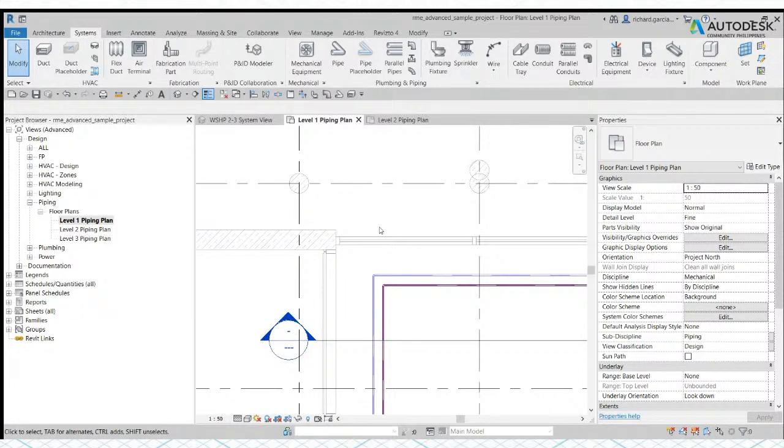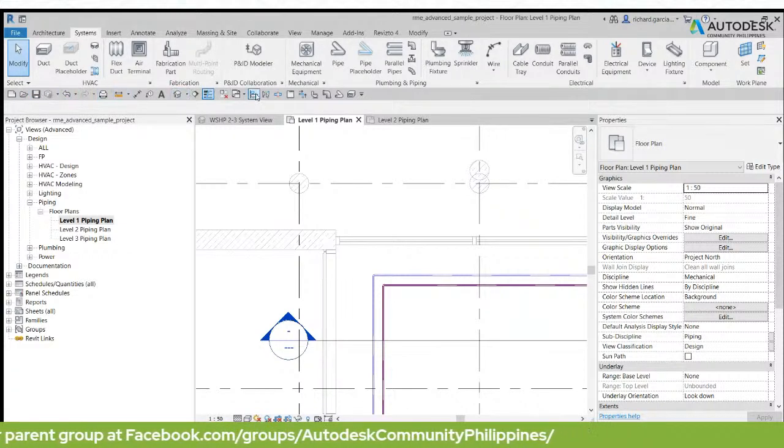Okay, so basically this is the basic user interface of Revit. So just a quick review. This top portion here is our title bar, and this is our info center on the right side. Then we have the ribbon tabs, and then we also have here our button, and then we have our ribbon panel, and the quick access toolbar, and the options bar.